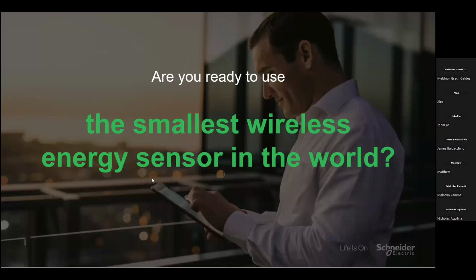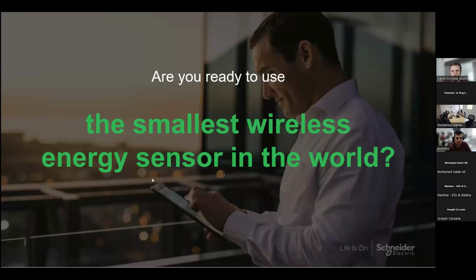Any questions? For the minimum current the PowerTag can read, I have just checked the technical data sheet. For the 63 ampere, it's 40 milliampere. This is the minimum current. For the 160 ampere, it's 100 milliampere. This is the minimum current that can be read. So it depends, and I guess it's very small, so with the smallest load, it can also sense the current. So 40 milliampere and 100 milliampere, it's very sensitive. Okay.